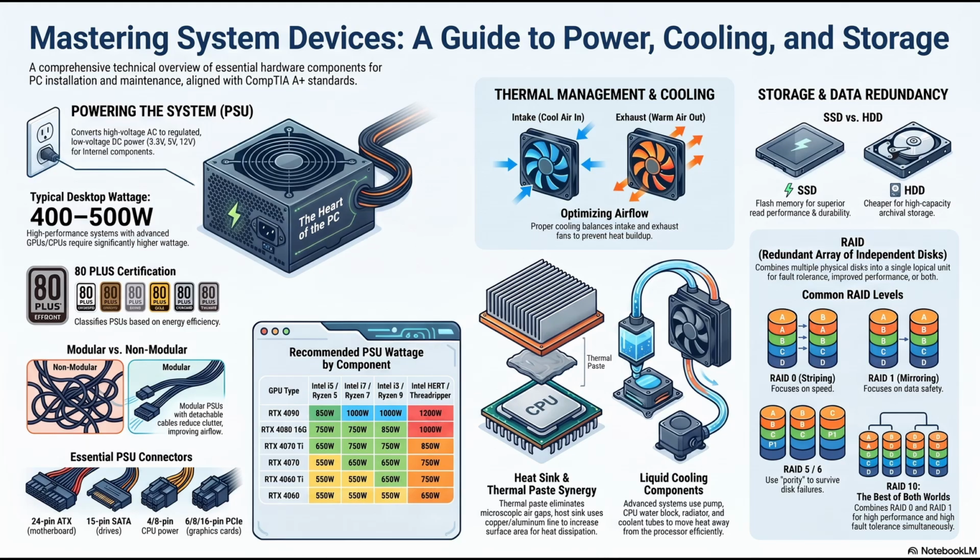Thermal paste, or thermal compound, is a highly viscous, thermally conductive fluid. It's often suspended with microscopic particles of silver, ceramic, or carbon. You apply a tiny amount, about the size of a grain of rice, to the center of the CPU. Then you screw the heatsink down. The mechanical pressure of the mounting hardware forces the paste to spread out, squishing into all of those microscopic valleys, displacing the insulating air and creating a perfect, unbroken thermal bridge between the chip and the cooler.